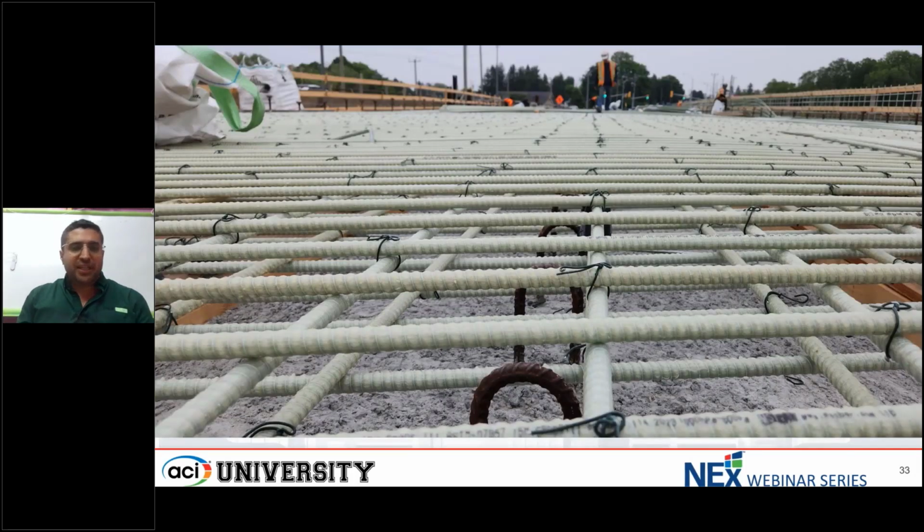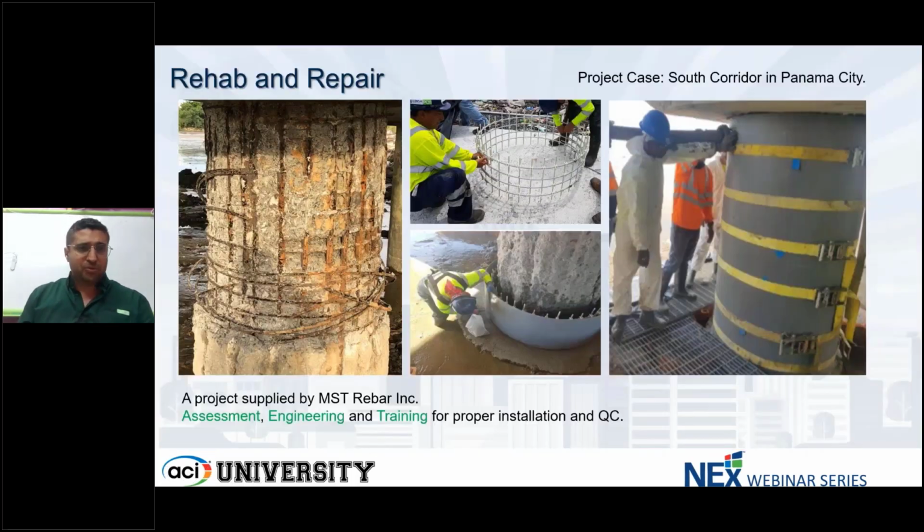The material is tied together with coated tie wires. People ask how we tie these together. Oh, do we need significantly more ties? As you can see, you don't necessarily need to tie every corner. You skip one, tie the other one. So same way as traditional steel reinforcement, and nothing is supposed to change.